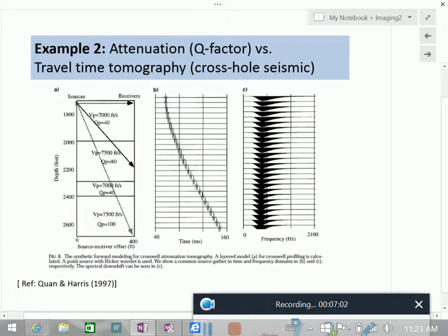So what we are looking at is tomography in the field. If you are doing tomography in the field, in geotechnical or in site characterization, typically, to put the transducers, you have to have kind of boreholes. So you drill a hole and you lower down your transducers, which will be geophones most of the time. They are called geophones, lower frequency, they measure velocity, etc.